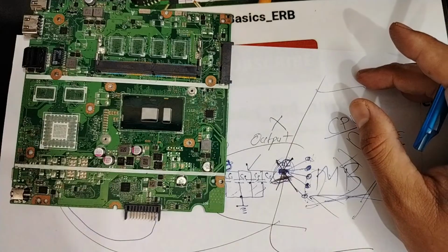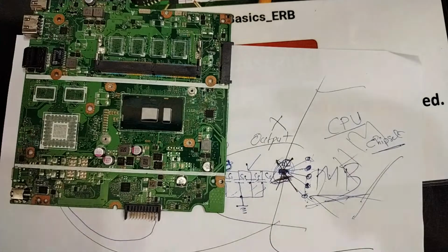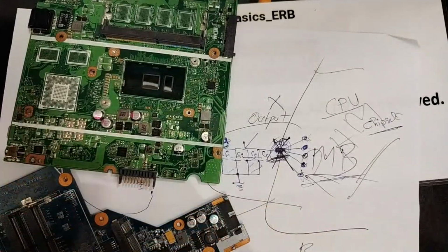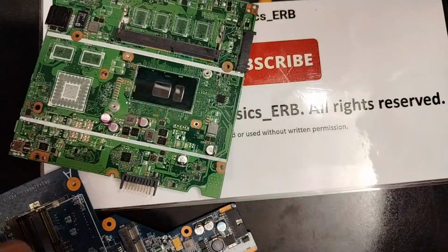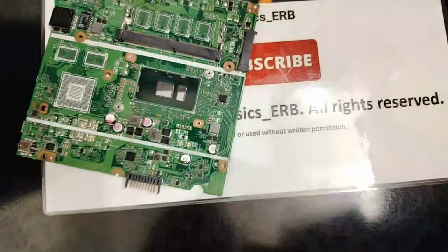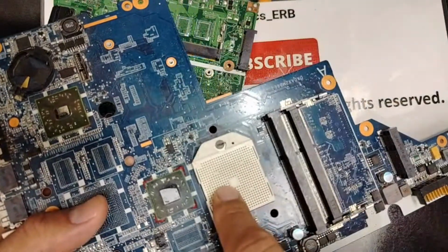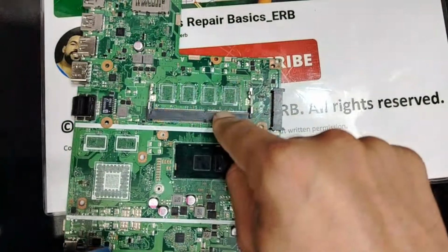Do you know, guys? Sometimes some technicians don't pay attention to the CPU socket. Guys, sometimes you can find that the CPU socket is shorted. Not just components. It could be the CPU socket. It could be the slot in this case.